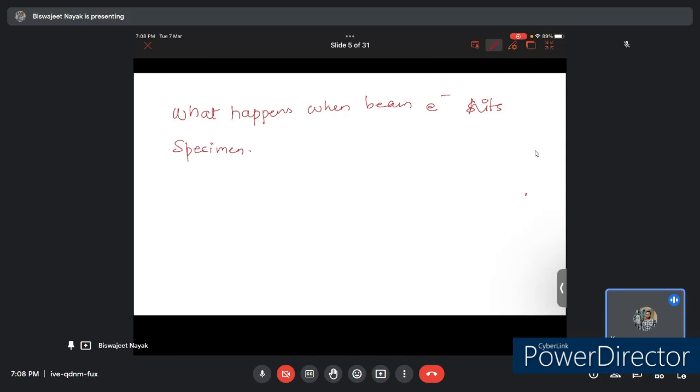As we know, by selecting properly the operating parameters for SEM electron guns, we can manipulate the aperture and the characteristic of the focused beam which reaches our specimen surface, and eventually we are able to control the energy, diameter, beam current and convergence angle of the same.